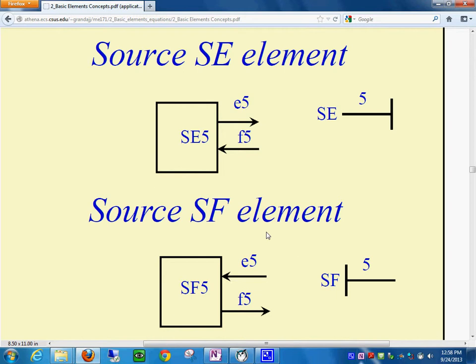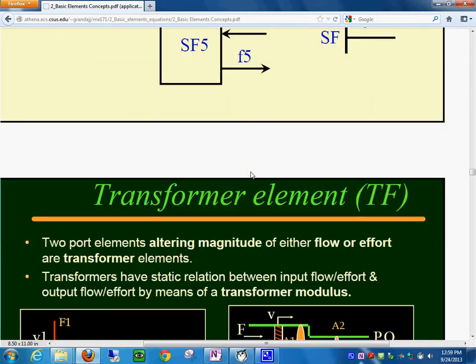So we have covered the two sources. Now, one thing I wanted to say is that when you go to Simulink and use one of these blocks, the other might be suppressed because it is assumed to be zero. But we know that the effort and flow sources and other elements interact with each other using the bond graph notation. So I'm just saying that in case you're doing it manually, when you go to Simulink, you don't need to put two signals. It's important because I have received that question in the past.